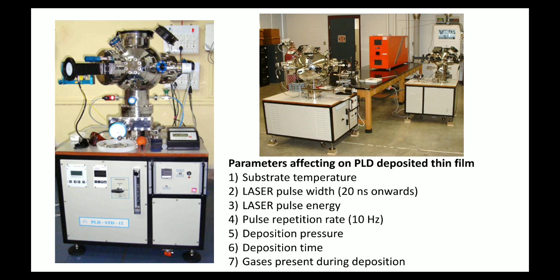You switch on the laser machine, and once it is on, you can control it with the controller, deciding how many pulses you want to use, 5,000, 10,000, or 15,000 pulses, or what frequency range you want to use.